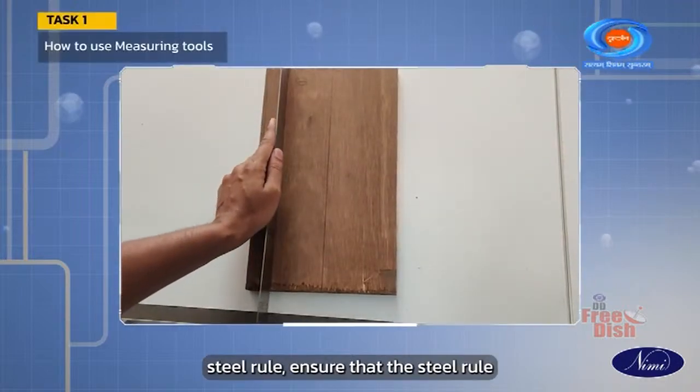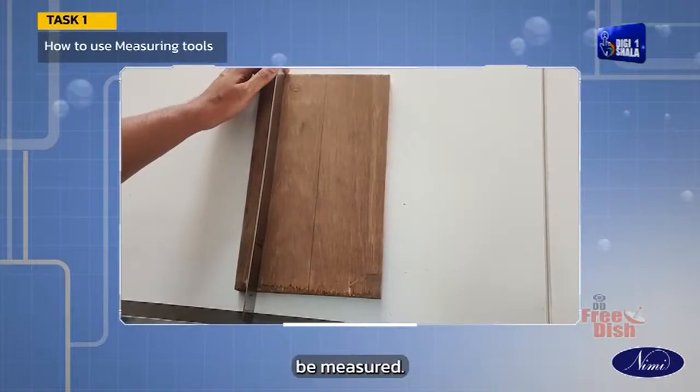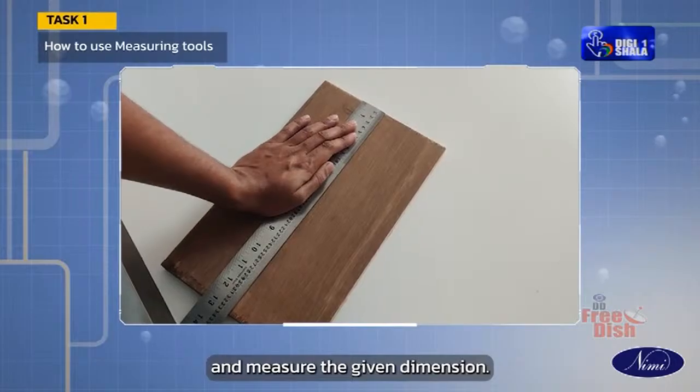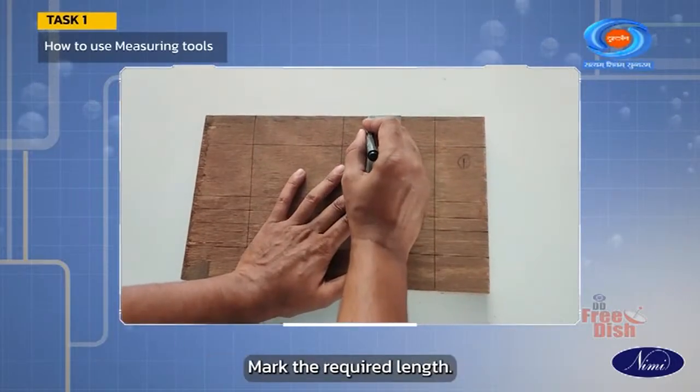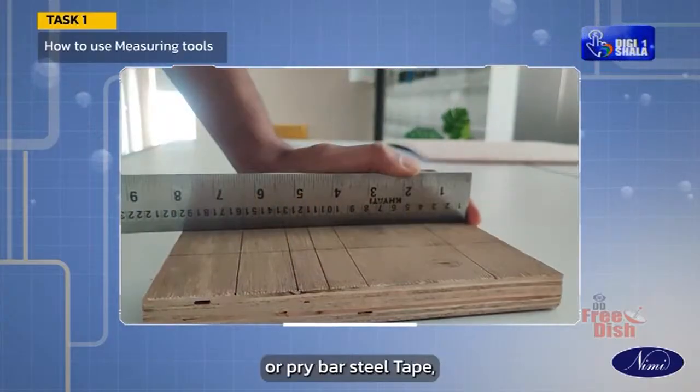Steel rule. Ensure that the steel rule is kept straight across the object to be measured. Place the steel rule on the workpiece and measure the given dimension. Mark the required length. Do not use the steel rule as a scraper, screwdriver, or pry bar.